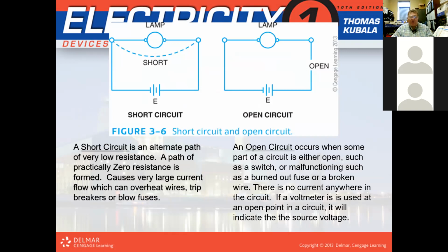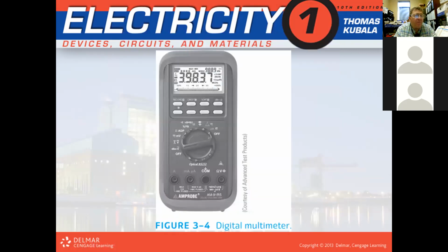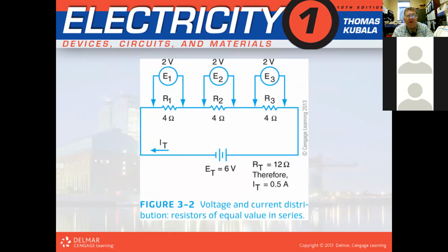Now, I will explain this since you're hanging on with me, and that will complete this chapter as far as the lecture. And I will help you with the worksheet Tuesday when you come, if you've got questions. You're going to be wiring your bulbs up Tuesday like this. You're going to be putting them in series. Not that you would normally, but you could, and you're going to see the brightness change and see it get dimmer. The bulbs help you learn these rules very well. You're going to have 3 of those hooked up in series, and things are going to change drastically in what you see.